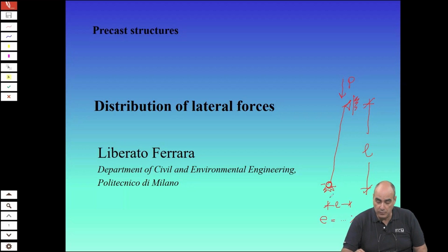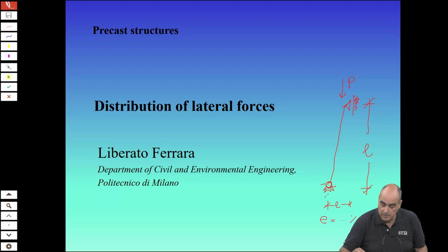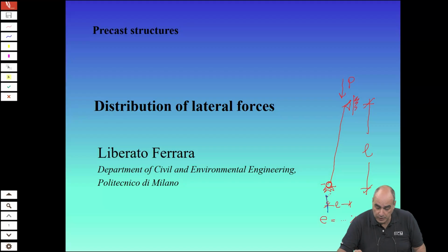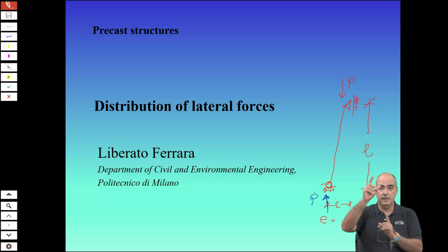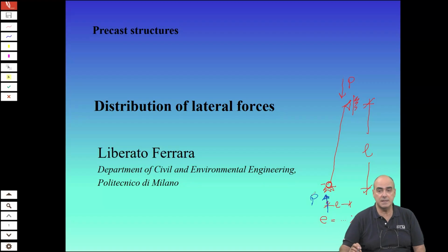Well, because of equilibrium, let's see. We know that we have a vertical force here equal to P. But you see, those two forces are no longer aligned along the same line. They form a bending moment equal to P times e. And this bending moment is clockwise.